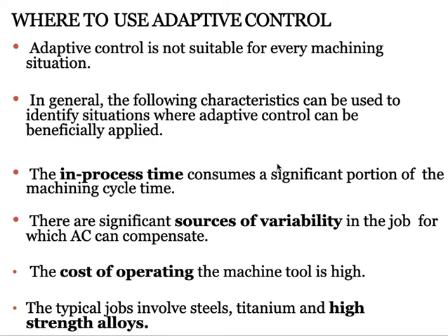If you see, the main advantage of NC/CNC is that it reduces the non-productive time in a machining operation. This time saving is achieved by reducing workpiece handling time, setup of the job, tool changes, and other sources of operator delay or machine delay.